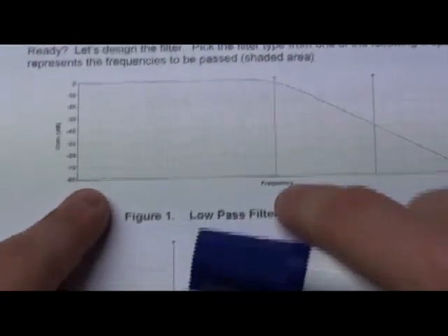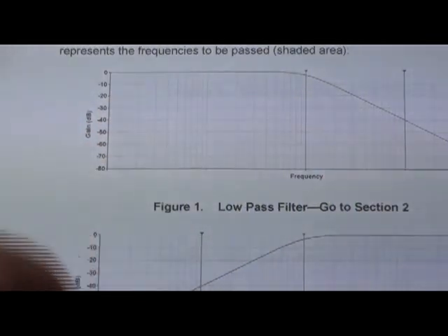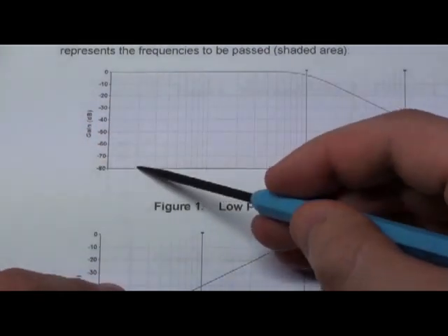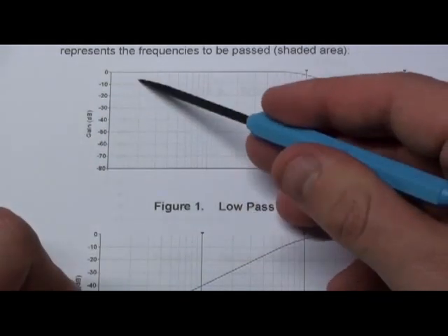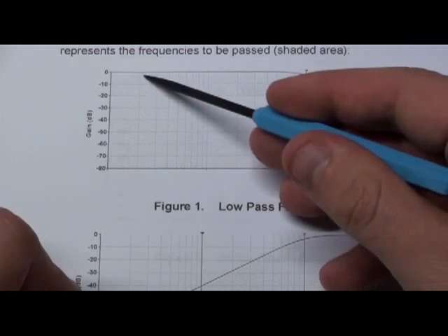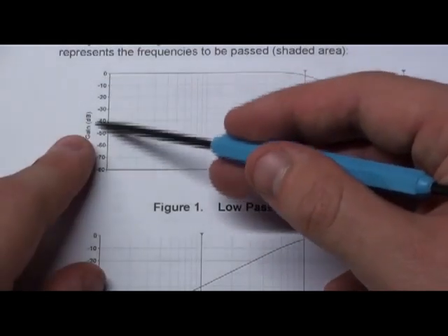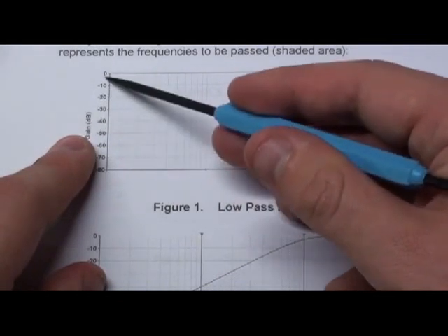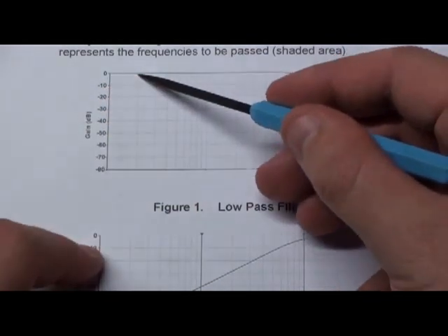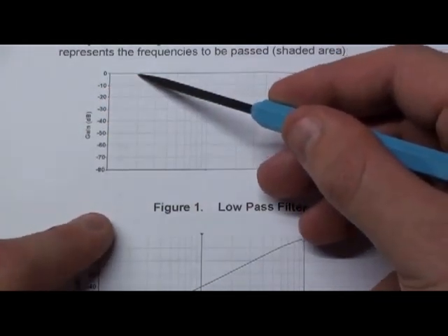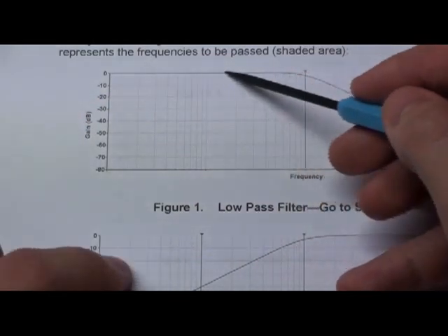So down here, if we assume that this line here is 1 Hertz, and we put a 1 Hertz signal, just a sine wave, into our filter, then it will, and this is in decibels so don't get confused, do nothing to a 1 Hertz sine wave. So it will multiply it by 1. And it will be the same as we go along.